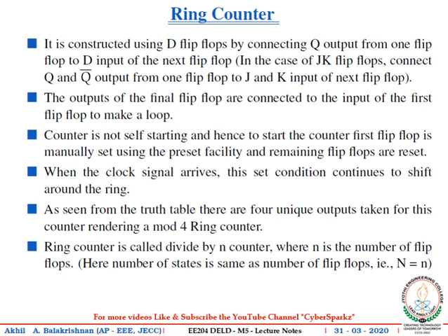One more point to be noted in the case of a ring counter circuit is the counting sequence of a ring counter. Adjacent flip-flop outputs in a ring will be either set or reset. For example, if you have a 4-bit ring counter and the first flip-flop is set and the remaining 3 flip-flops are reset, then on each clock pulse, this set flip-flop output will transfer this 1 to the next flip-flop, and this pattern will continue. That is, if the initial output is 1 0 0 0, the next output will be 0 1 0 0, the next output will be 0 0 1 0, and the pattern continues.